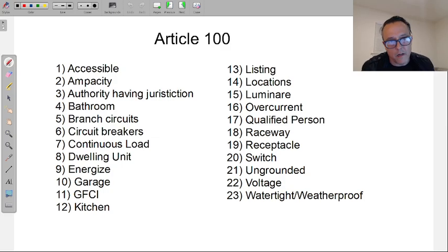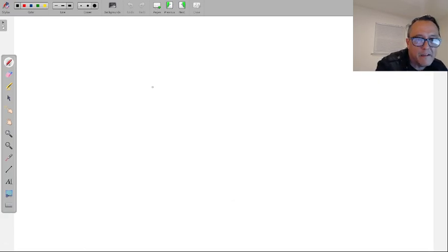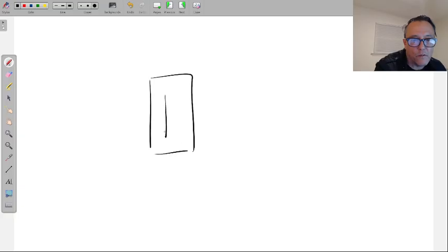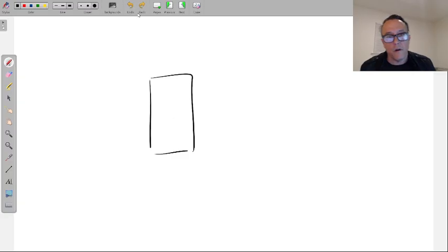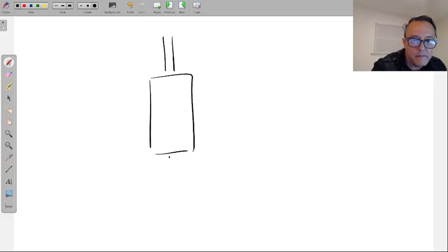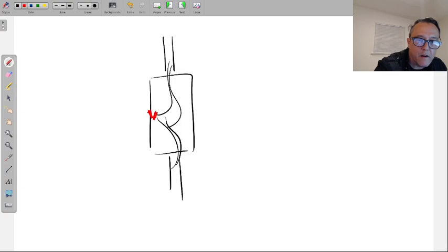And people try all the time. They just try to put a splice there and bury it behind drywall. This happens a lot of times when, for example, there's a switch on the wall. A person might have a switch on the wall, a little on-off switch setup. And then they get rid of the switch and move the switch somewhere else. But the electrician has these wires in there, they're just in there, all spliced with the little wire nuts that we have.